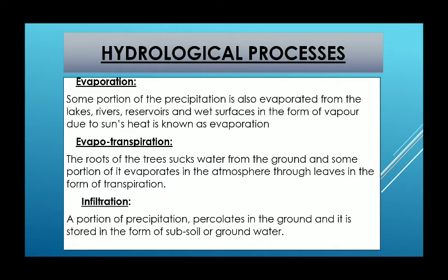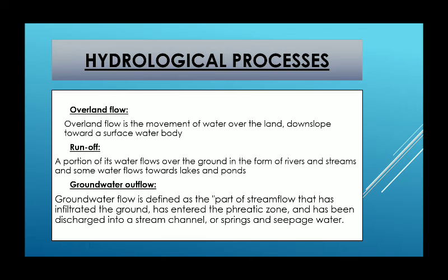Infiltration is the process by which water on the ground surface enters the soil. It is governed by two forces, gravity and capillary action. Infiltration rate is a measure of the rate at which a particular soil is able to absorb rainfall or irrigation. The rate decreases as the soil becomes saturated.